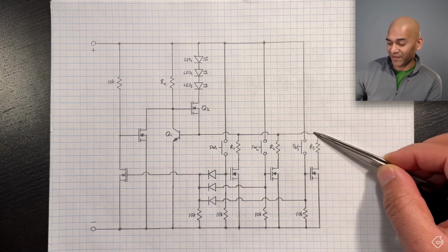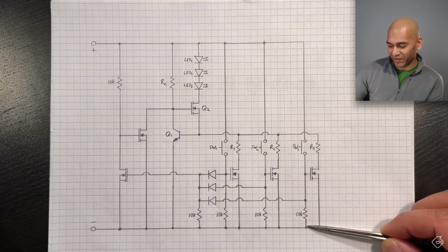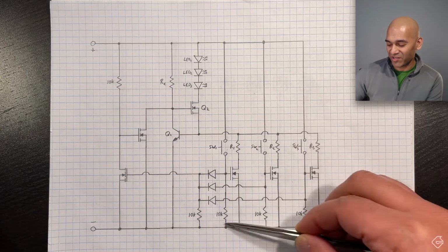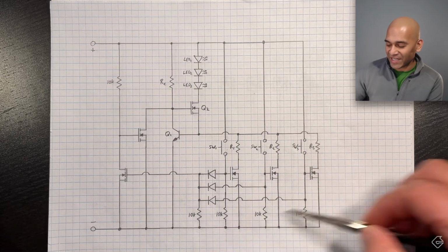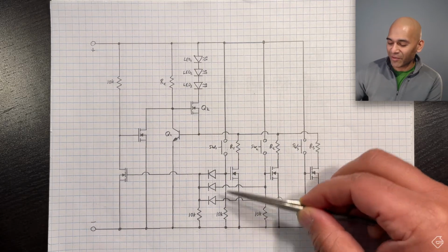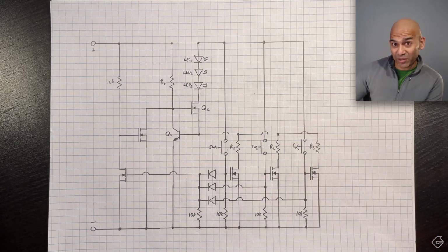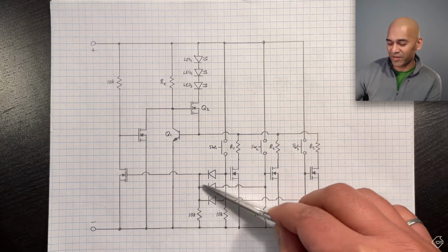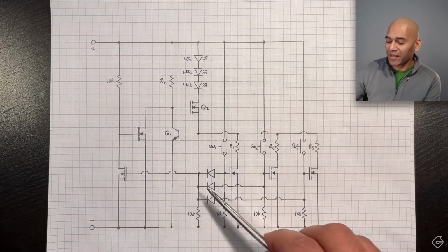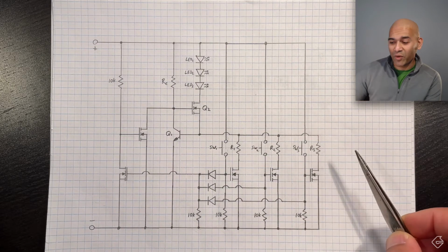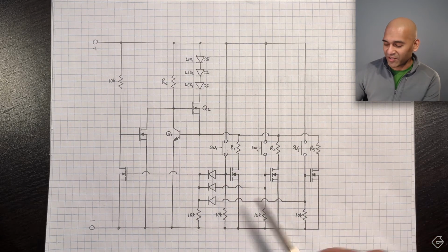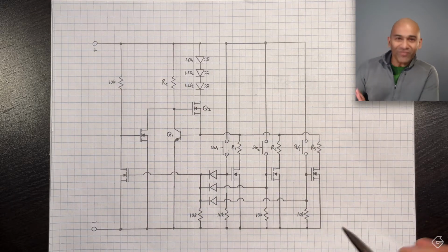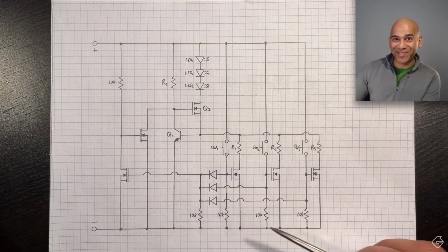The other thing that I've also done is I've added another circuit path over here. And when I did that, I also noticed on closer inspection that these 3 resistors over here were actually unnecessary. The reason they were there was to make sure that these MOSFETs get pulled down to 0 when these switches are not pressed. But it turned out that this circuitry over here is to ensure that when no buttons are pressed, the lights are completely off. So the fact that we had this is already bringing the gates of those MOSFETs down to 0. All of that to say that we didn't need these 3 resistors. So I took them out.